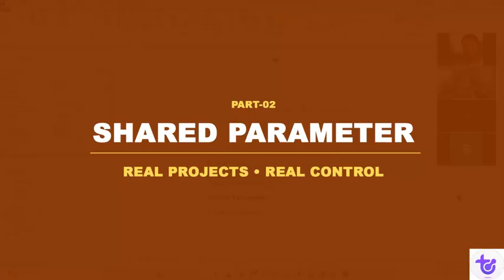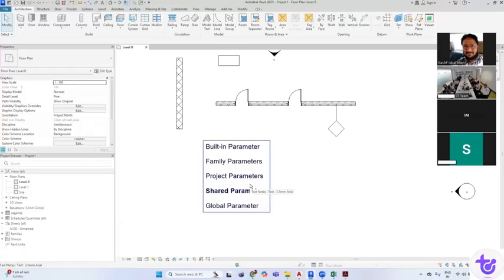Moving forward, now it comes to the shared parameters, because the requirement was to have a parameter which has a scope across the project and the family. Even if we created it in one family, it should appear in the schedule in the project. Also, the same parameter can be tagged. That means that particular parameter can be accessible in the tag family itself. So that is why there is a common txt file being created while we create a shared parameter.